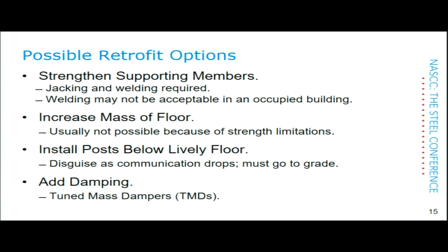I tried many years ago every way possible to figure out a way to strengthen joists, for instance, using bolted construction, using turnbuckles, and it's just not possible. Humans are extremely sensitive vertical vibration sensors. 10,000ths of an inch right now where you're sitting, you would be uncomfortable. You would mention it or possibly even complain about it. Okay? So we're trying to reduce 10,000ths of an inch to 5,000ths of an inch.